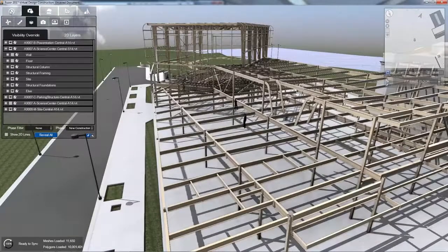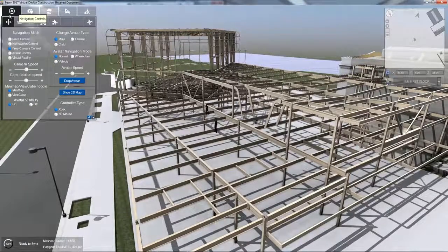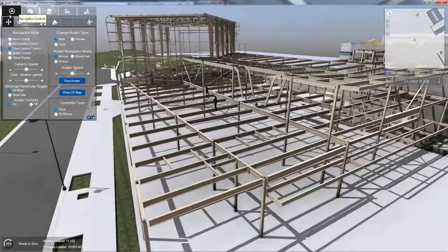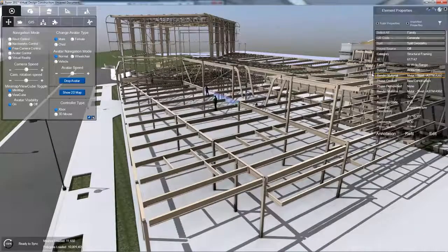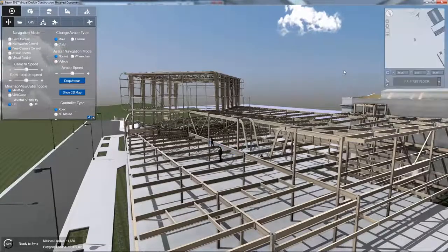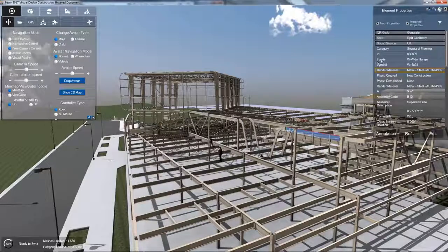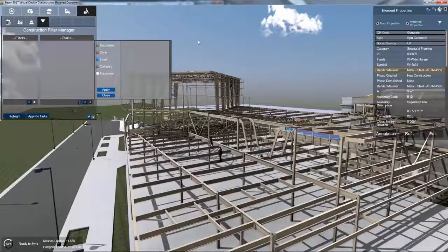Now let's say I want to auto sort. What's becoming a popular mode in terms of workflow process is to take your objects and add a specific custom field in there. One of our clients actually adds a custom field that's a timestamp for all the objects as they put them in, so in here it'll say something like timestamp or underscore TS, and it'll give a value for that. What we have the ability to do inside of Fuzor is sort by any of these categories. Now what that can also mean is that I can auto sort by those categories.